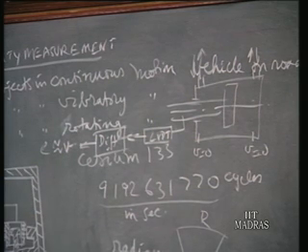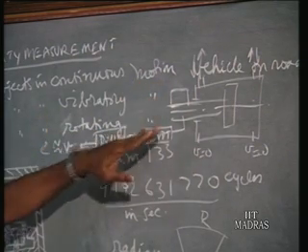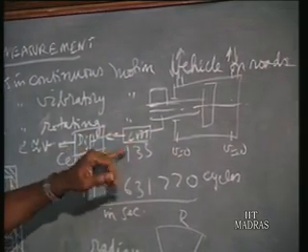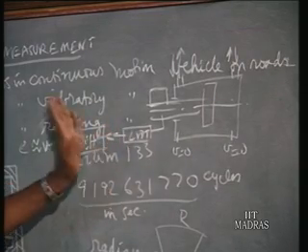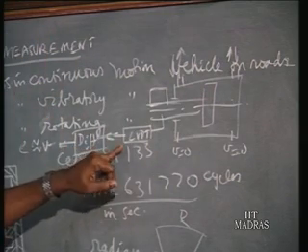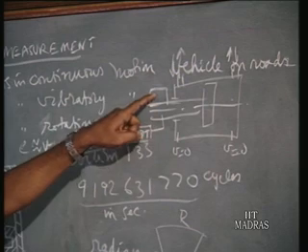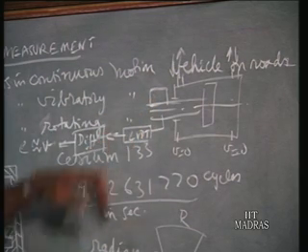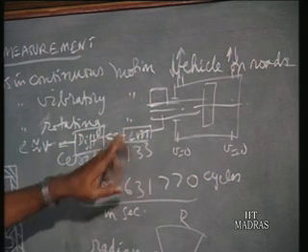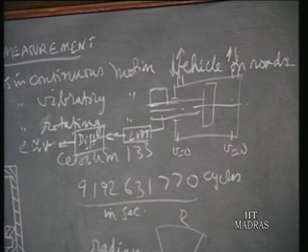Or we can also integrate, by mounting an accelerometer on this moving body and integrating the acceleration, we get the velocity. You can adopt any one of these two, but the problem with the differentiation is, we know from the LVDT the output voltage will have some ripples, 5% ripples, because that signal comes out of the low pass filter. That ripple, when it is differentiated, gives rise to peaks called noise in the velocity measurement, whereas in integration of acceleration such noise will not be there. Hence integrating an acceleration measurement is more suitable than differentiating a displacement measurement. So that is one method.